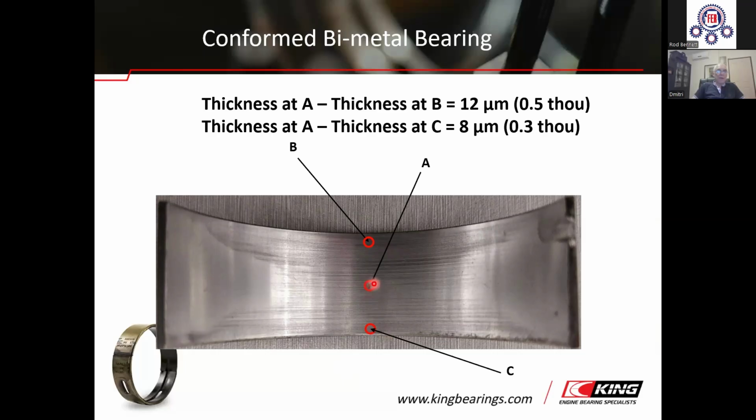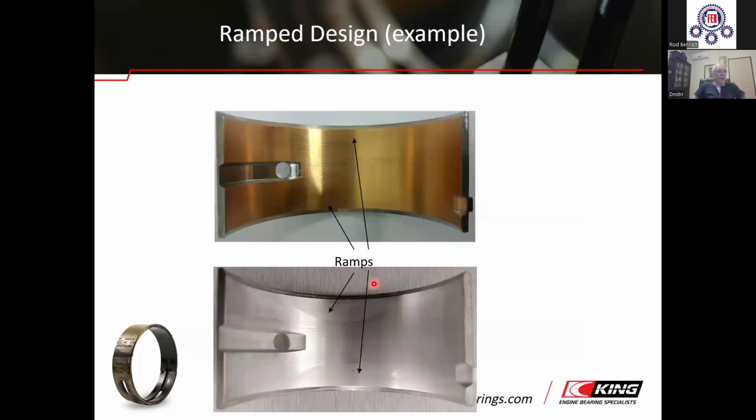And after that, the bearing obtained the profile which conforms to the profile of the bent shaft, and after the conforming process, the bearing continues to work in hydrodynamic lubrication regime. Sometimes, in some bearings, the inner profile is designed and fabricated with edge ramps, like here and here.